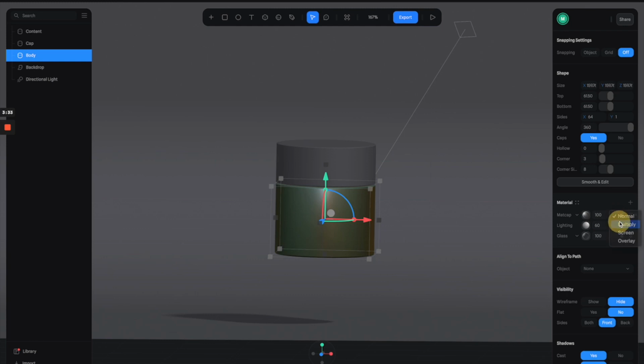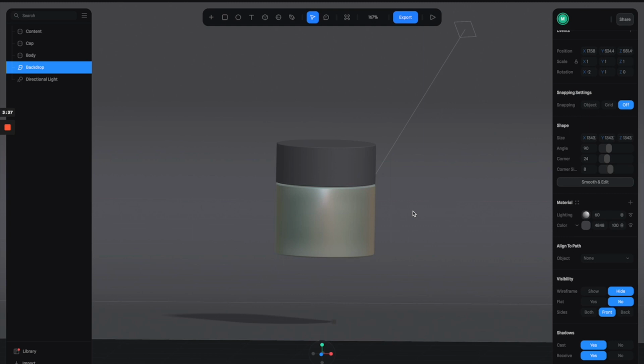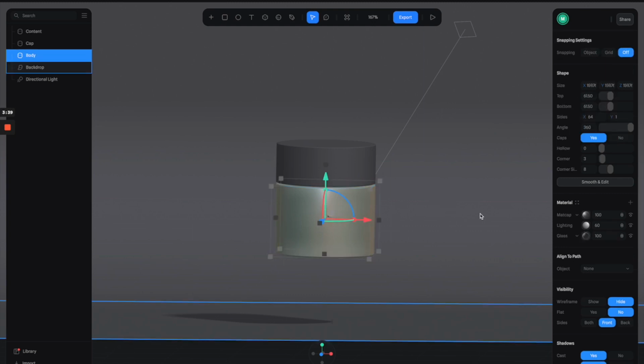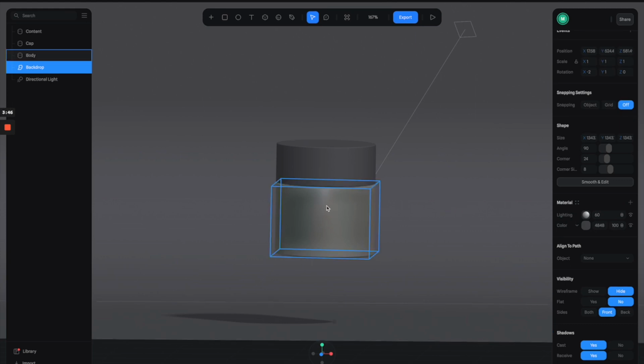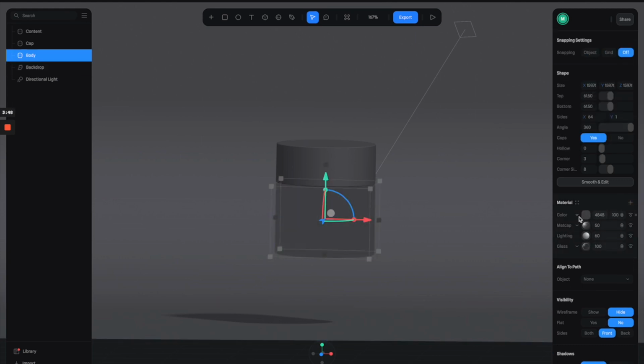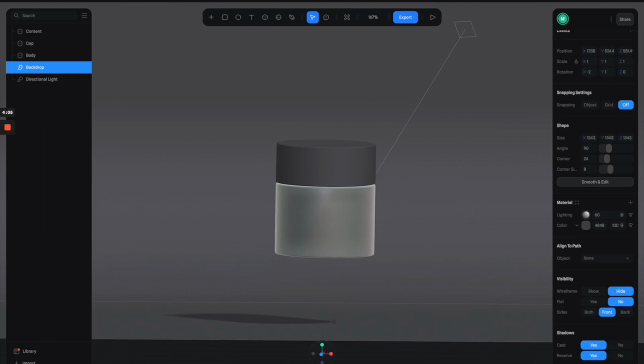And you can also play around with these blending modes. So let's try multiply, too dark, so maybe screen. So yeah, screen's looking good, so I'm going to go with this. And then let's reduce the intensity by 50%. So we have something like this. So I'm going to create another layer, and for this one let's select Fresnel. Where is it? Oh, right here. So we have a Fresnel layer here. So let's reduce it to 60% opacity.